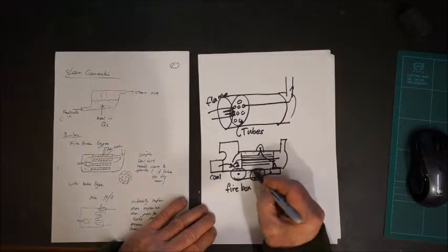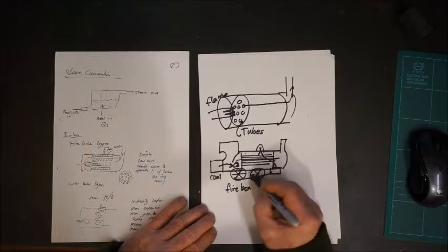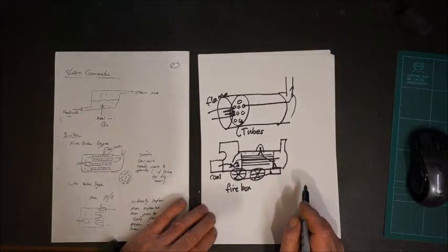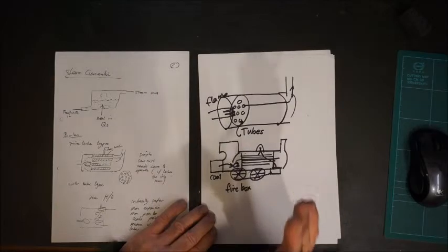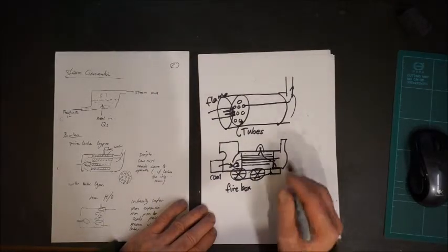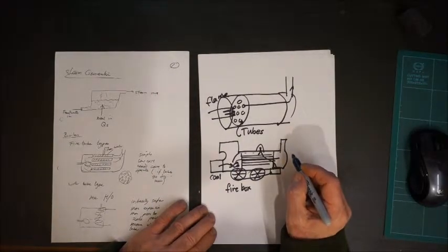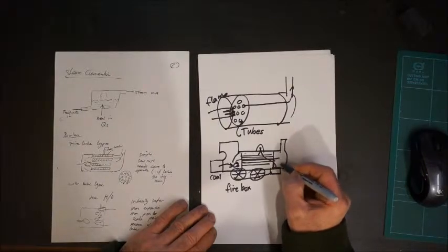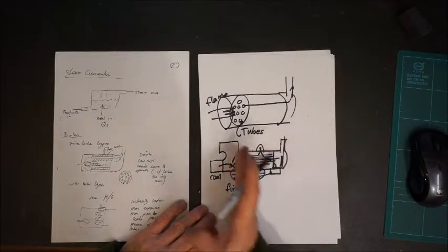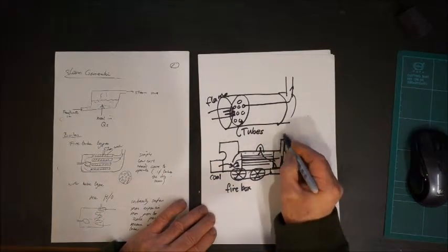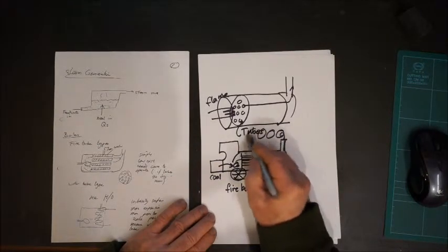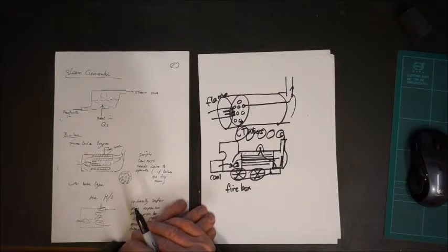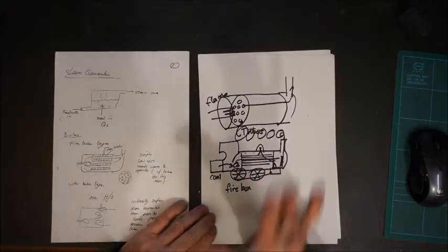As I say, there's some very nice little animations and pictures in the online things that I've given you. One little comment is the chuffing sound that a steam train makes is the steam coming out of these valves, and also some steam is blown up the chimney, and this steam blowing up here sucks air and flames through the tubes. So of course if you look at a steam train you'll see the sort of chuffing effect coming out there. Anyway, the point is it's a fire tube boiler.